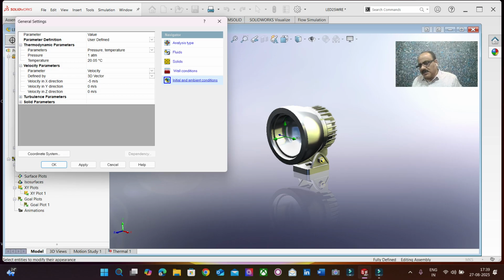So we define it in such a way that we gradually increase it. From 0 to 1 second, 1 to 2 seconds, 2 to 3 seconds, it's going to increase, and from 3 seconds it's going to rapidly shoot. The temperature is going to abruptly increase, and the rate of change of temperature from 3 seconds to 5 seconds is increased by 2 times.